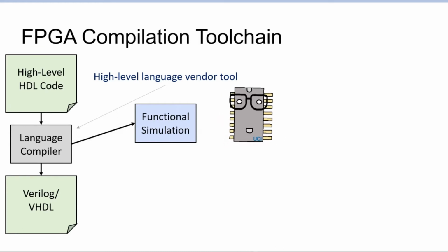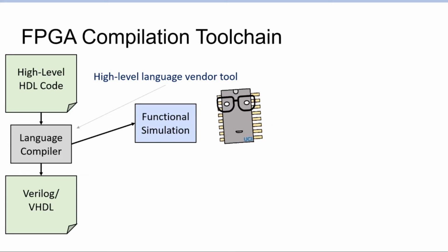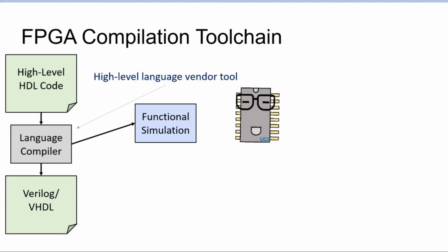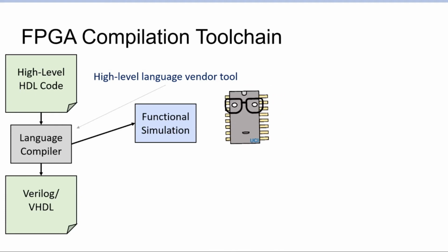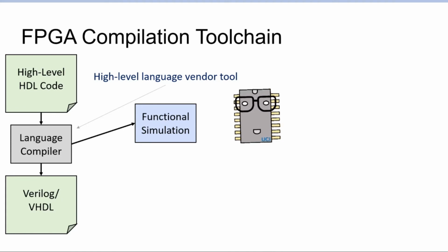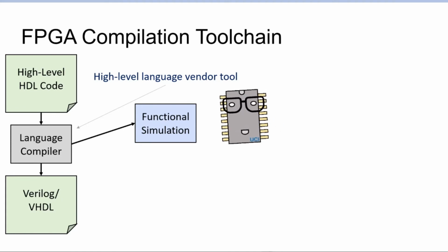If you simulate a very low-level language like Verilog, the result of the simulation is pretty much just, at every clock cycle, the waveform of the values on the individual wires between these modules. It's good, but if the design is very complex, it's sometimes difficult to make sense of all of this.